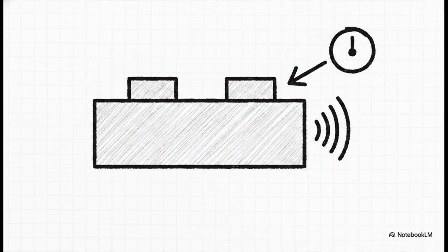The dual-gate MOSFET. By literally dropping a second gate in series, the overall input capacitance is drastically slashed. This makes it an absolute powerhouse for high-frequency RF amplifiers. Plus, that second gate gives engineers a dedicated input for automatic gain control, meaning they can dynamically adjust the amplifier's response on the fly. A real game changer.